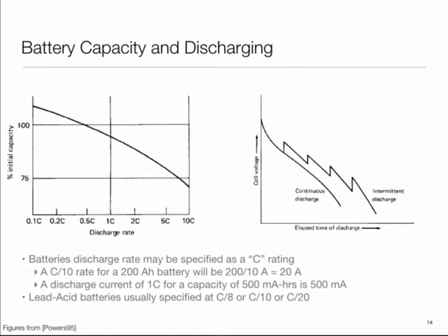And then finally, these kinds of techniques. All of this management is done by something called a battery management system. In simple devices, it's essentially non-existent. But when you look at laptops or cameras, it gets more sophisticated. And by the time you're looking at something like an electric vehicle, it is really complicated. It's essentially a control system. It has at its disposal a bunch of batteries, and it has to come up with an optimum policy of how to extract energy out of them.